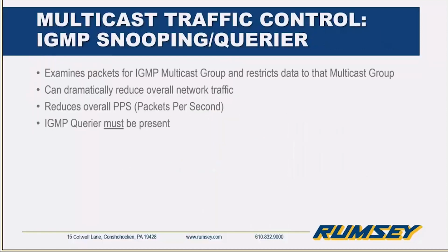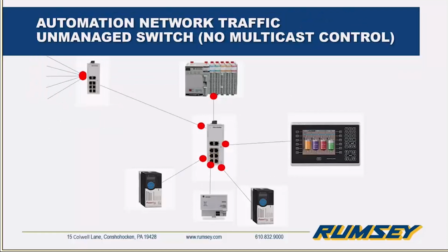And I think that is a critical animation right there, because how often do you see that is one of the key situations happening on the plant floor, that there's a series of unmanaged switches all acting in this manner, broadcasting traffic everywhere. That's pretty common for detrimental situations, right? Yeah, absolutely. We see it every day, all the time, and the common thinking was, okay, the switch works fine on its own, but what happens when you start connecting devices?